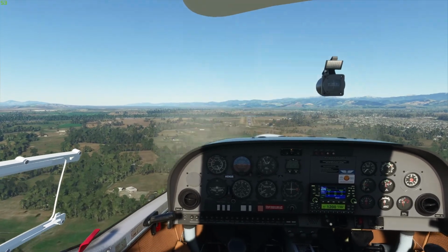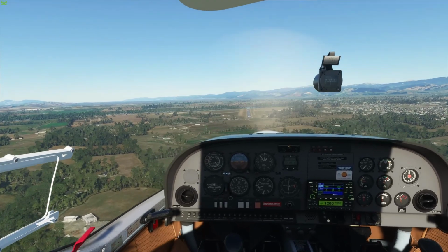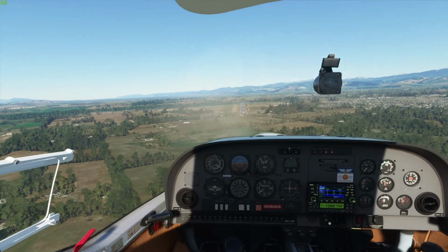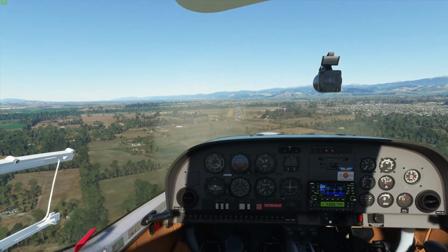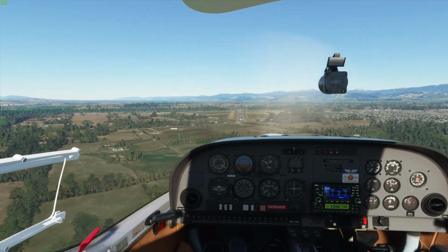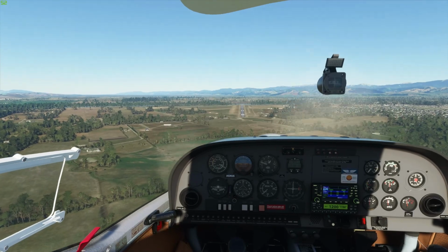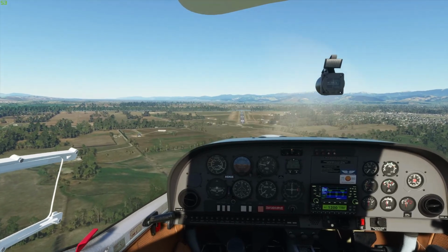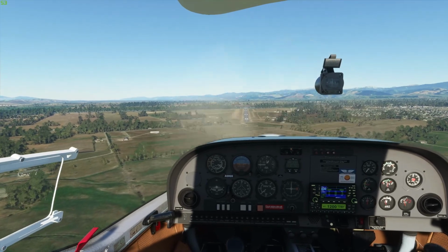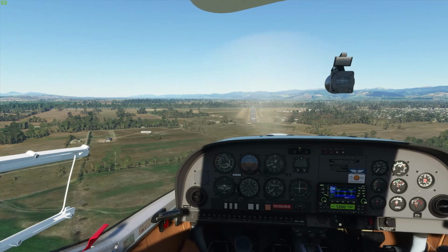Go to full flaps there, and the speed should come back to around 60 knots now with full flap, and a similar attitude, slightly more nose down. You see it's quite twitchy in the pitch there as we are making the changes. And I think the little bit of turbulence isn't helping. But that's about right. 500 feet a minute, 60 knots, and the power's back around 10 inches.